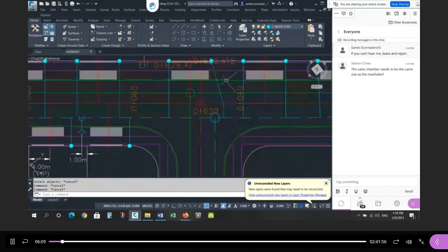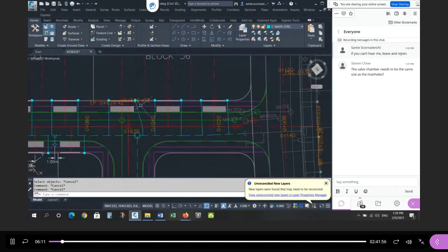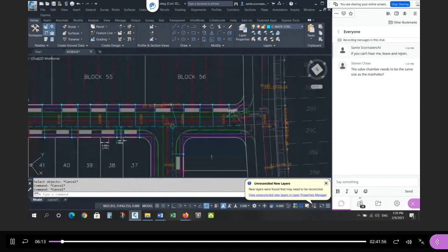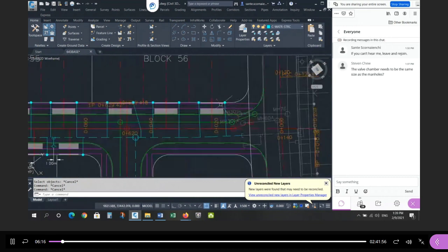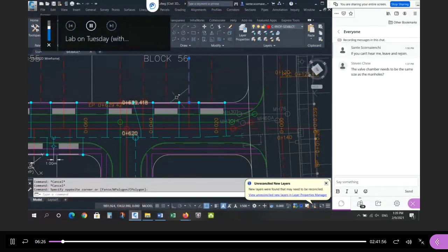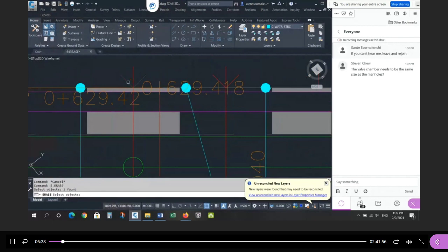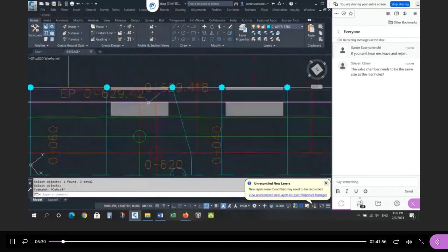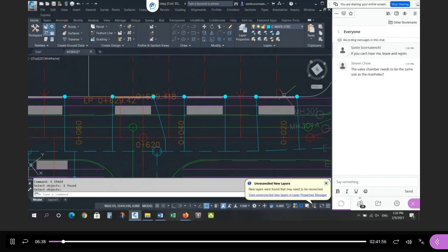Okay, so this was a common one here. So the solution I used, I left the driveways paired. So on the surface, they all look the same. But underground, what I did is I moved the service connections, the doubles, I moved the doubles over so that these two units and these two units have a common point. And then what I did here is I offset the 2.5 typical off to the side, and I had a single connection under the driveway on this side, and I did the same here.